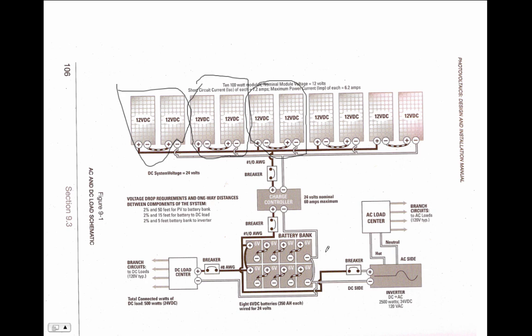But just to show you how this all fits together. Maybe it's a little complicated. Maybe I can let you just look at this for a minute. And I think this is pretty much the last slide, yeah. So I'll let you just look at this for a minute so you can think your way through it and see if you can see the series and parallel connections here in the solar panels and the batteries, and how the voltages add in series, to get the proper system voltage. And then once you have the proper system voltage, you have to add the capacity.